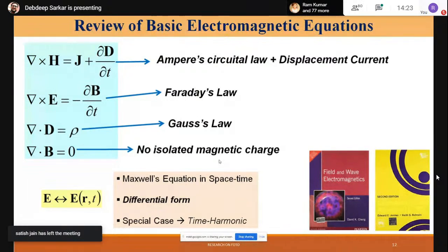If you plot it, it is infinitely extended in time. But whenever we operate any real device, we switch it on at some point and we switch it off at some point, right? And when we switch it on, there is a transient. So although the assumption of e power j omega t gives us very useful results, and helps us a lot in designing systems, we should keep in mind that in real life, we will not always have the time harmonic scenario.